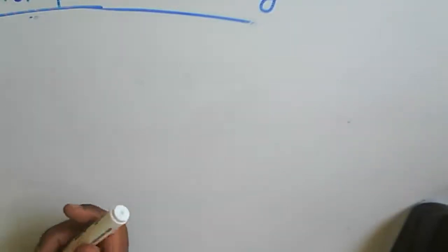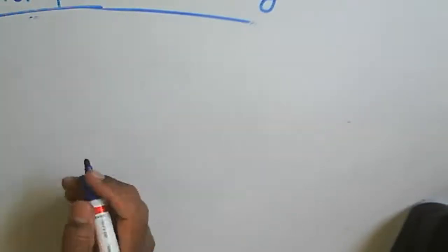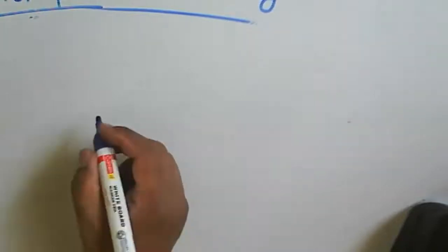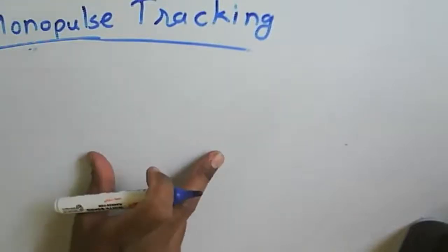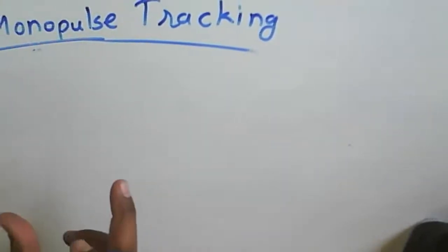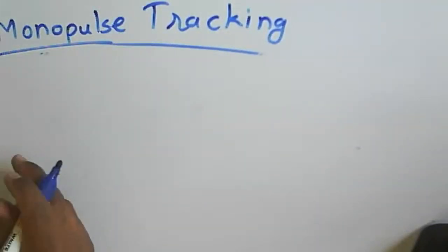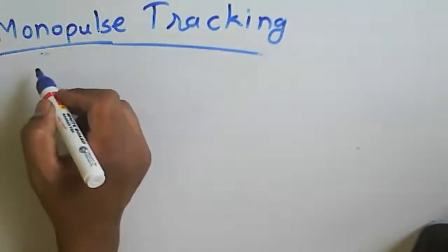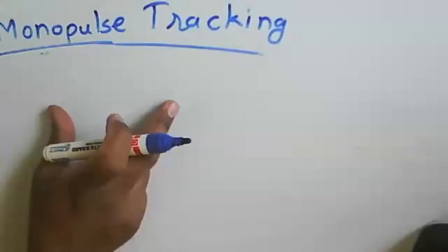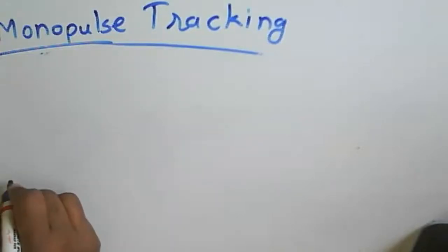So we consider how this measurement is carried out for the sum as well as the difference signal. We simply draw a diagram that shows the difference channel as well as the sum channel, which will be useful for transmission and reception for the tracking of a target. Generally we consider monopulse here, and this is about monopulse tracking, which compares only the amplitude.